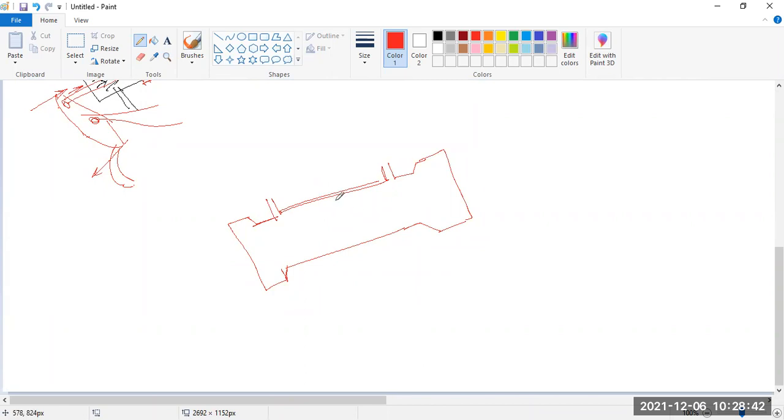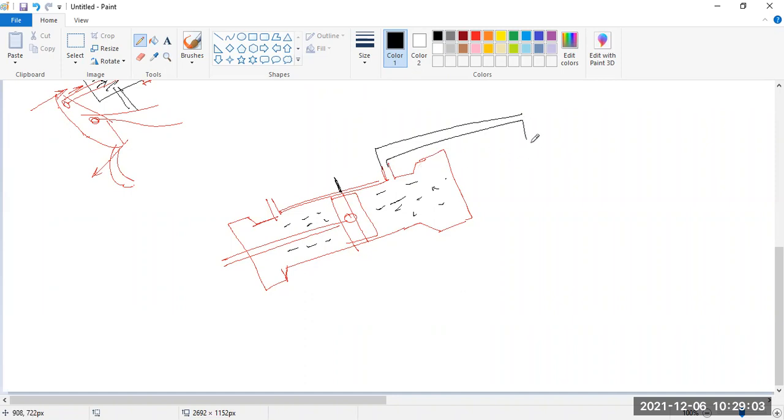So this is your piston, this is your simple piston. Whenever the fluid on this side and the fluid on this side are the same, the piston is at this middle position, this is the neutral position. But if you push with your pump, channelized by this valve, to this side, fluid is incoming over here and the force is gathering over here.